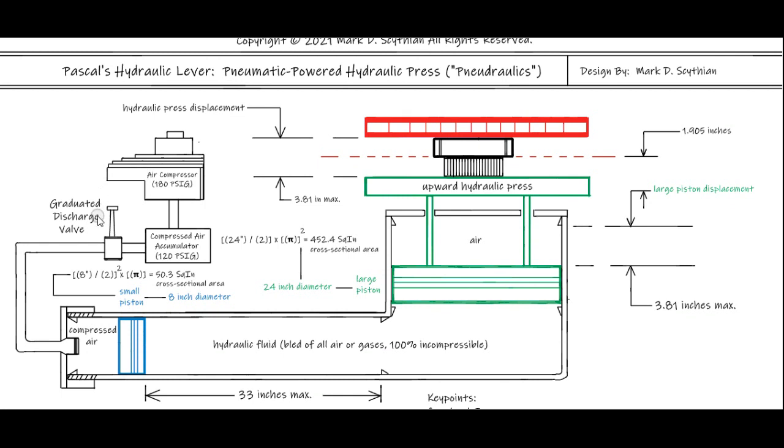So this could also be connected to a sensor, and position sensing on the application can then trigger the prescribed air pressure charge in order to induce the input force required for some predetermined force amplification output.